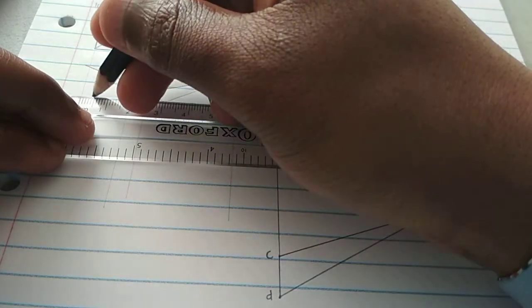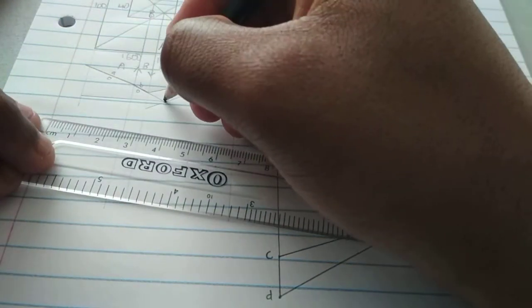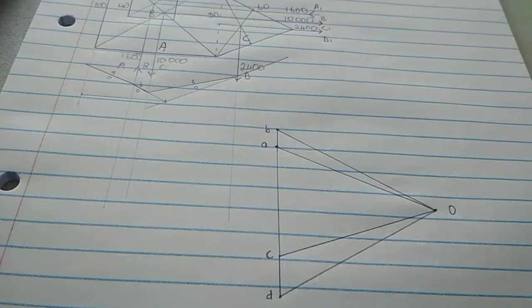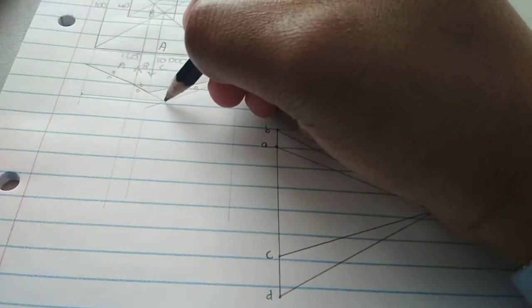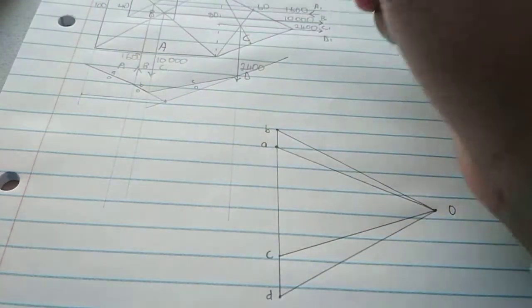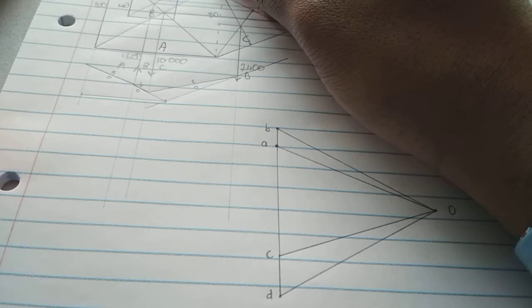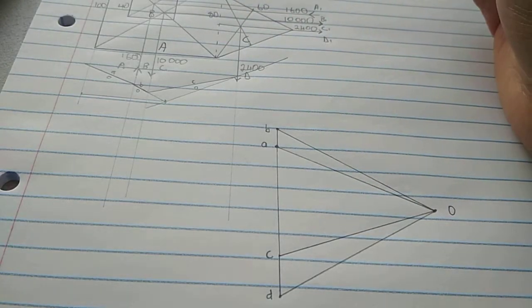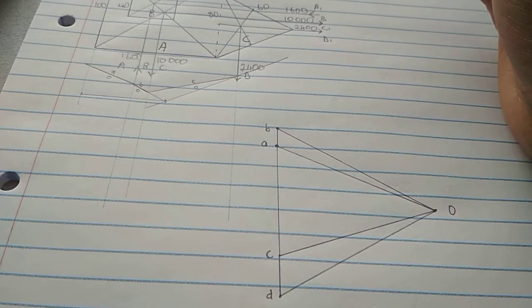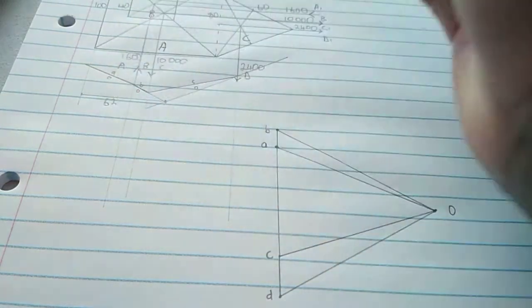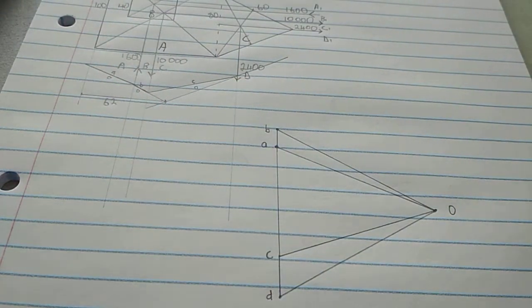So from there to there, to the centroid on the X, measures about 31. So we need to take it back to our scale. So we'll multiply the 31 by 2 to get the actual centroid, which is 62 millimeters. All of these are in millimeters.